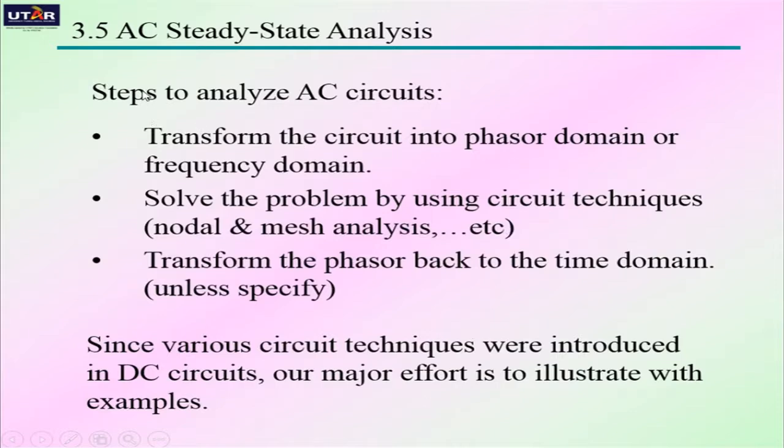Here's a summary of the steps we need to apply to analyze AC circuits. First, we transform the circuit into the phasor domain or frequency domain, and then we solve the problem by using all the circuit techniques that we have learned, such as nodal analysis, mesh analysis, Kirchhoff's voltage law, Kirchhoff's current law, Thevenin circuit, Norton circuit, etc. Then we transform the phasor back into the time domain.